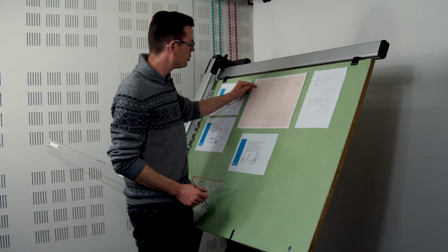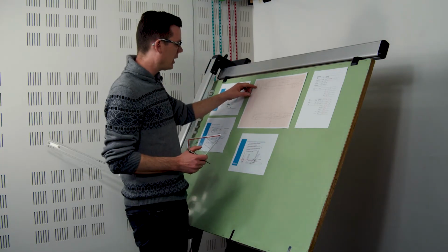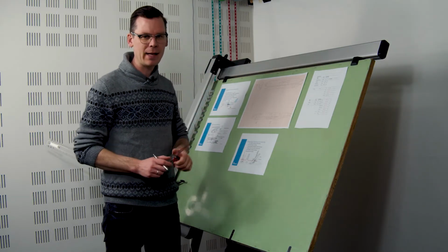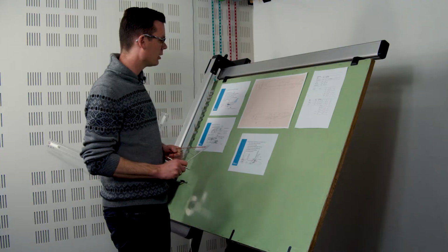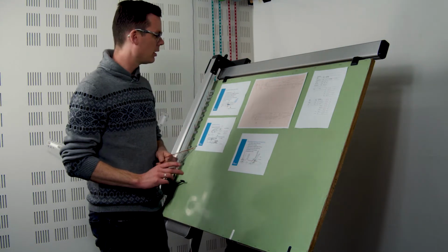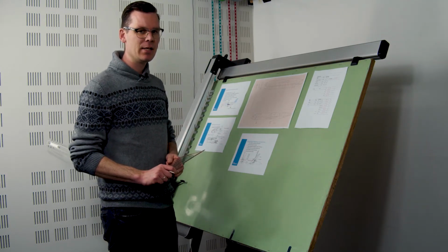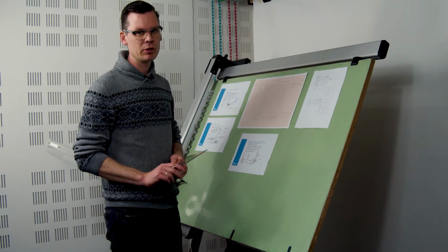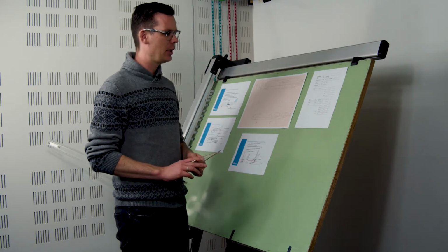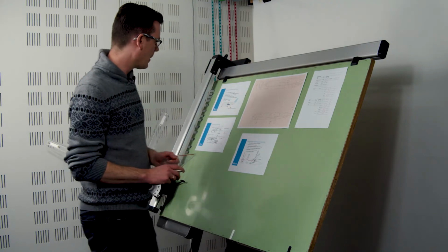So even if I would put my wheel 1 meter away from the center line laterally, it would already comply with this bank angle requirement that I impose here. The next requirement we're going to look at that might determine this lateral position of the main landing gear is the lateral tip over criterion.